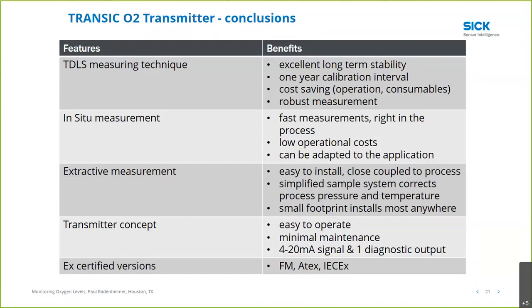And it's based on the transmitter concept. So it's very easy to operate, minimal maintenance required, and has a 4 to 20 milliamp and a single diagnostic output. Finally, it is FM certified to meet EX certifications. So it's a perfect installation in a chemical or refining environment. With that said, that's the end of my presentation. I would open it up for any questions.